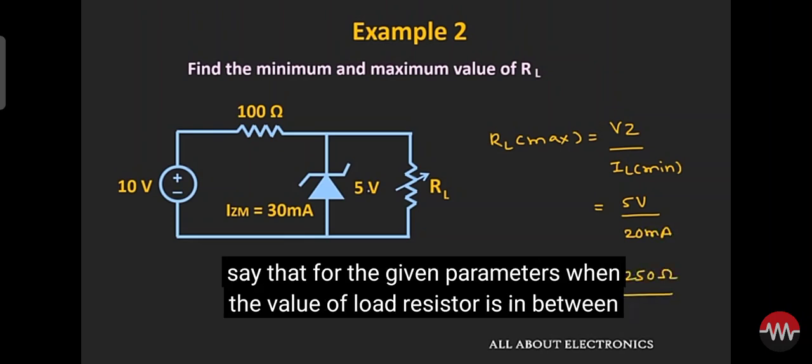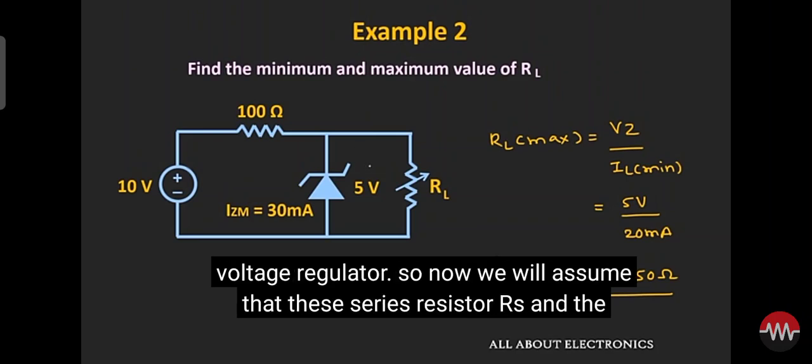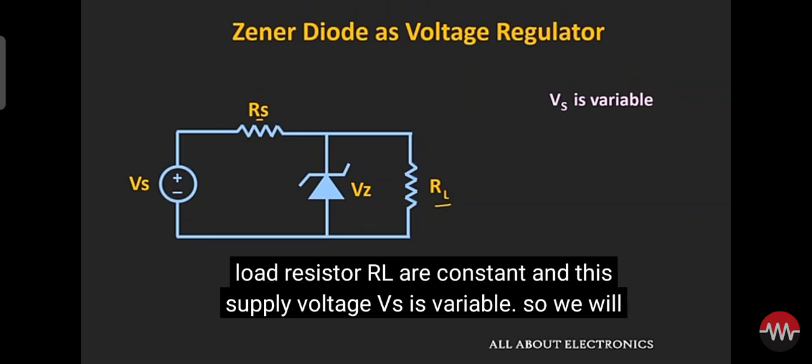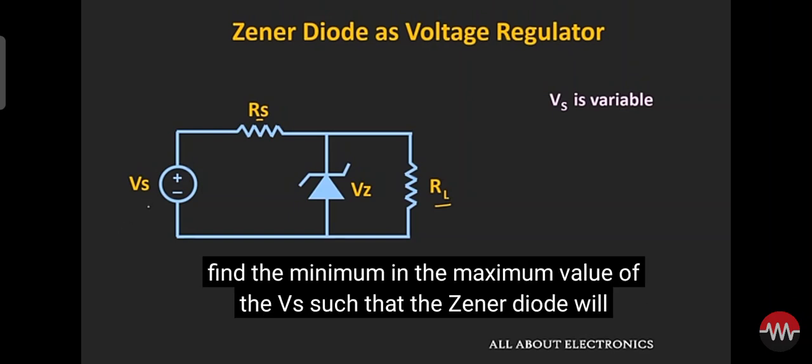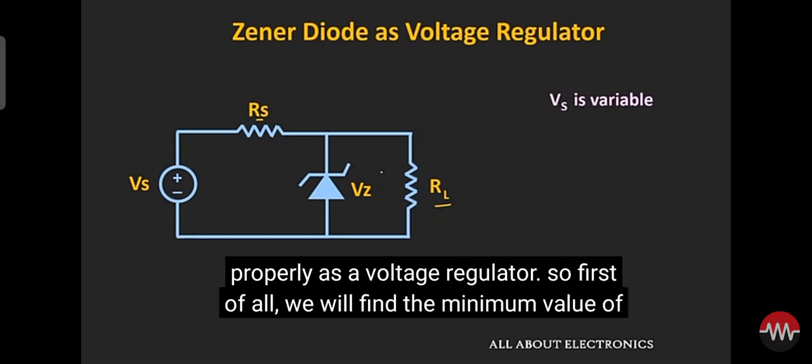So from this we can say that for the given parameters, when the value of load resistor is in between 100 ohm and 250 ohm, then the given circuit will work properly as a voltage regulator. So now we will assume that this series resistor Rs and the load resistor RL are constant, and this supply voltage Vs is variable. So we will find the minimum and the maximum value of the Vs such that the Zener diode will work properly in the breakdown region. Or in other words, this circuit will work properly as a voltage regulator.